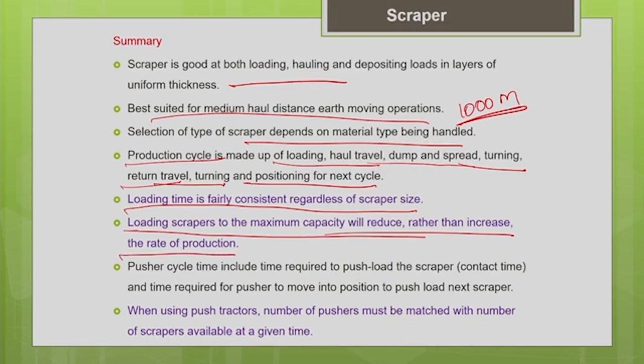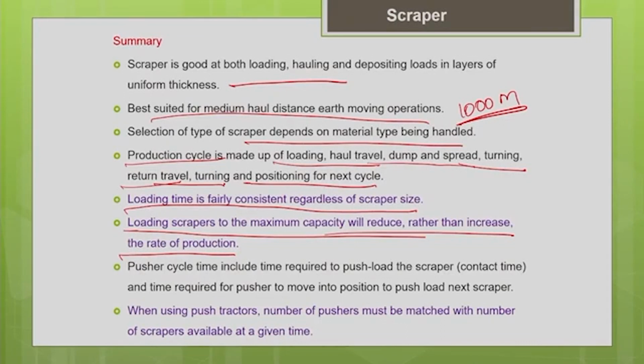We should not try to load the scraper to the fullest capacity, because as the scraper bowl is almost full, the incoming material will encounter resistance from the material already lying inside the bowl. Unnecessarily, it will increase your loading time. So don't try to load the scraper bowl to its fullest capacity. Find the optimum loading time from the load growth curve, which you can get from the equipment manufacturer, and follow that optimum loading time.